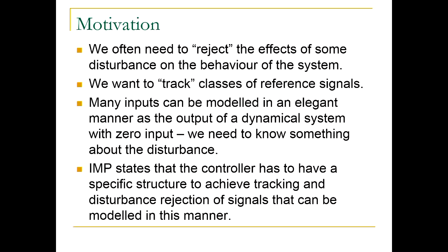It turns out that many inputs can be modeled in a very elegant manner as the output of a system or transfer function with zero input. We saw that for integral control in the last lecture. We will revisit that and then generalize it in this lecture to state the internal model principle for more general classes of inputs rather than just step inputs. So what is the internal model principle?